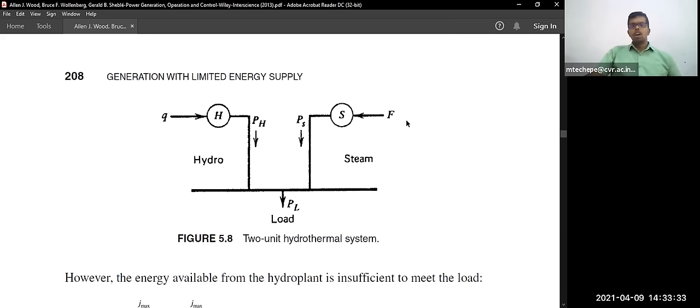If you join together, you have to tell from which unit, in 24 hours, based on the demand, in which hours you have to optimally utilize the generating units. That is the economic load dispatch, no? So for example, in peak hours you have to go for steam generating units.